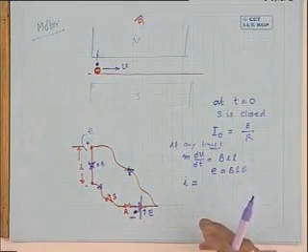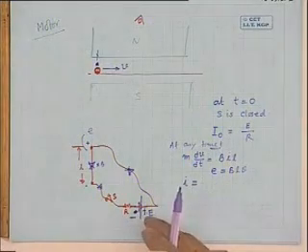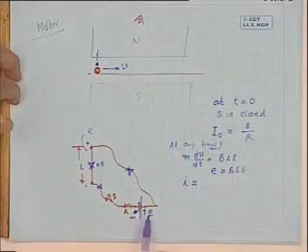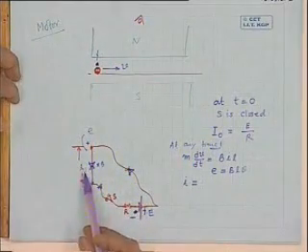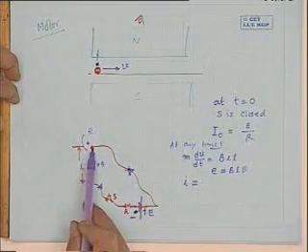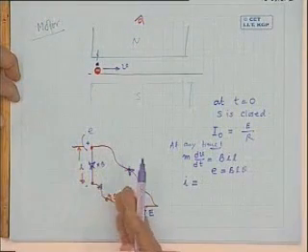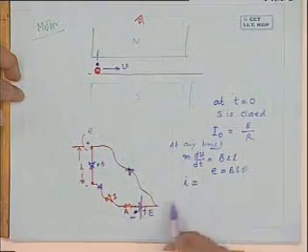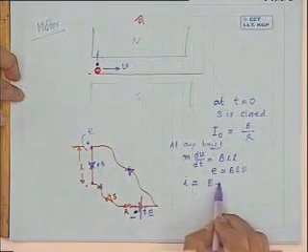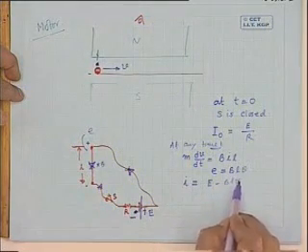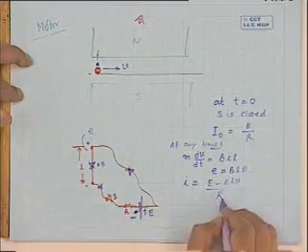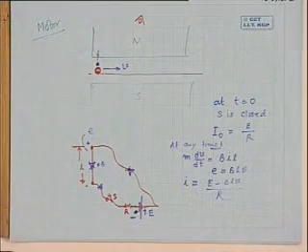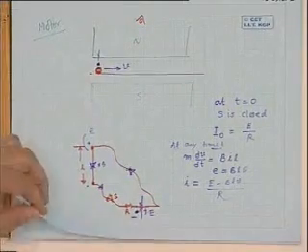So the moment the conductor is in a state of motion, the current in the circuit is no longer decided by E alone. Two EMFs are acting and they are in opposition: E and this induced voltage. That is what we call back EMF. So what will be the expression of the current? E minus BLV divided by R.